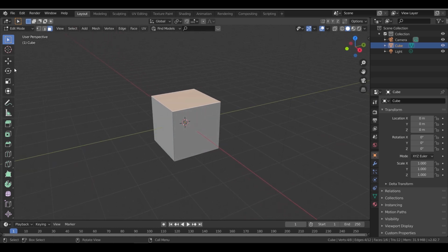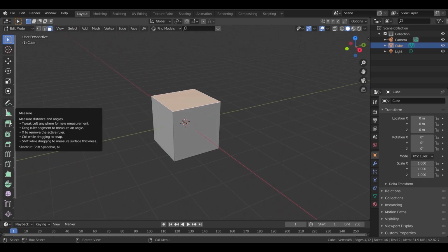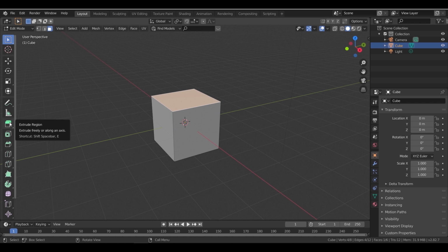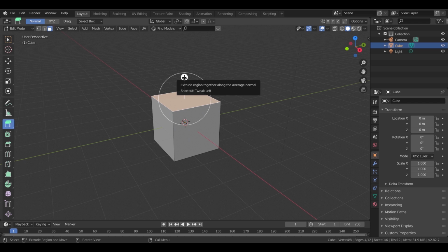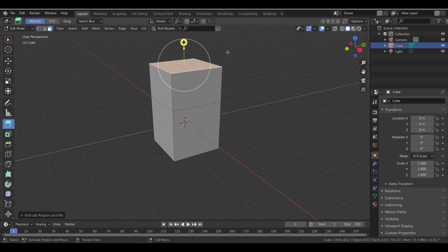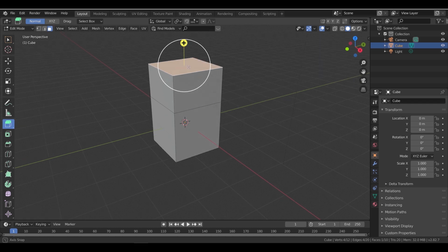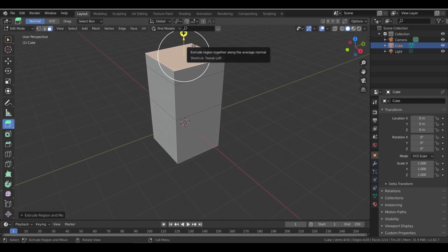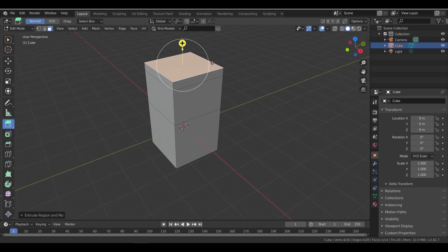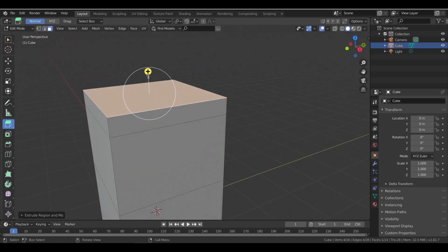So, to continue with the tools, the first in the new ones is Extrude. Now, if we hit it you will notice a plus icon over the face selected. With this, we can extrude this face and control the extrusion depth with this arrow. While this tool is on, you can select any face and extrude it.